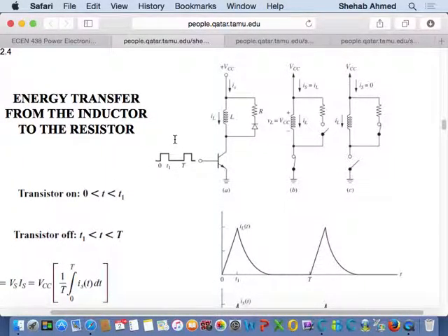But one circuit where you really need something like that is where you have a relay. You can buy relays. The word relay is a very common term that electronics people use. It's like a small box that you would buy, and it's basically a mechanical electromagnetic switch where you have a mechanical contact run by an electromagnet. So you have an electromagnet that pulls the contact or opens it up, and it's basically an inductor that you charge to create some magnetic field to pull or push a contact, right?